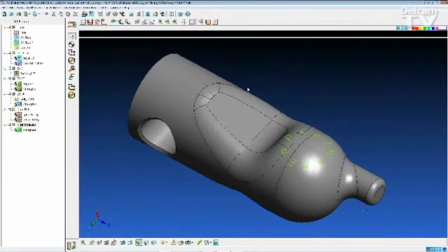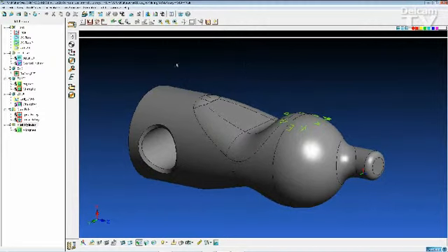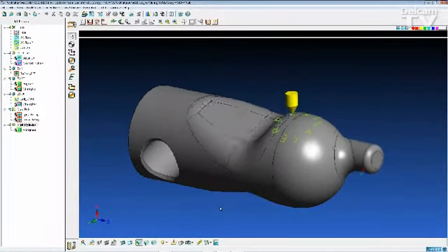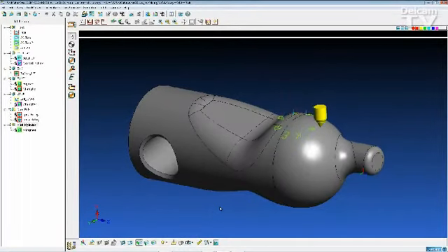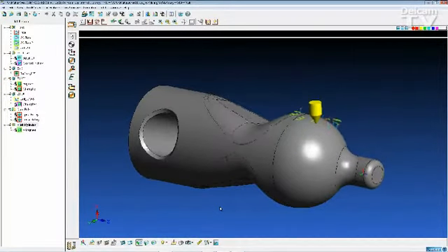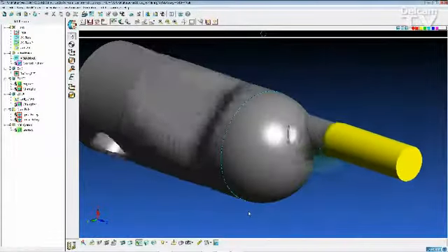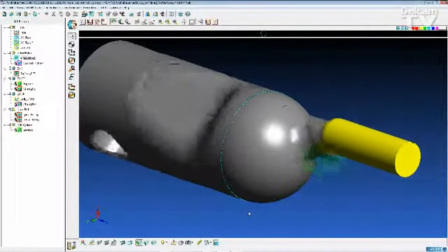We also have cylindrical milling. This will take a toolpath, and we're using projection. So we're projecting a cylindrical path down onto the part, doing some engraving in this case. Using the rotary axis, 3D machining. We also have polar machining using 3D offset.